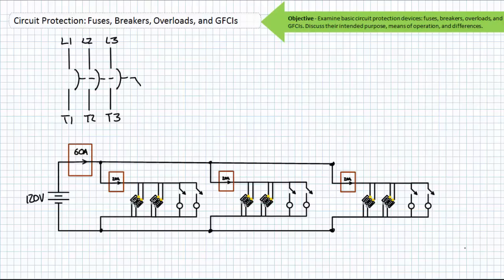Only those circuits that are exclusively fed by that circuit breaker are affected, allowing other portions of the system to run if needed. For example, the main circuit breaker, servicing a residence, affects all circuits, whereas the circuit breaker associated with just some bedroom ideally services only that bedroom. This allows other vital systems to function while you perform maintenance on the electrical system in that bedroom.